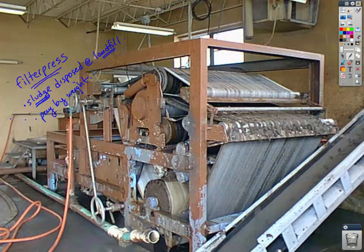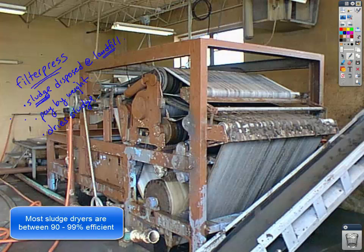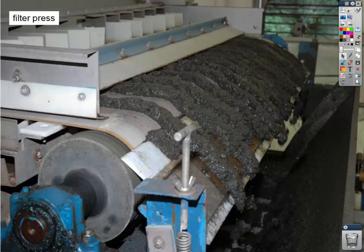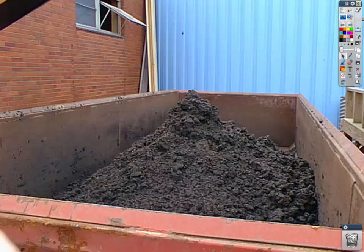So the filter press is the machine that dries sludge. And that's what you're looking at. So this big giant machine is all geared toward drying sludge. And here's the sludge on the filter press. It's moving through a conveyor belt looking process, but it's all about drying that sludge so that you can pay less to dispose of the dry sludge at a landfill rather than wet sludge. Here it goes. That's the sludge. It goes into a dumpster in the back, and the landfill company comes and picks it up.